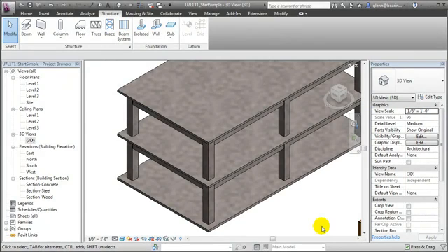From a construction modeling perspective, concrete tends to be easier to work with, because beams and concrete slabs can both be placed right at the floor level. As a monolithic material, these two types of elements will merge together just as they will when the concrete is placed. We still need to consider the accuracy of our beam spans. Let's take a look at how they're modeled.